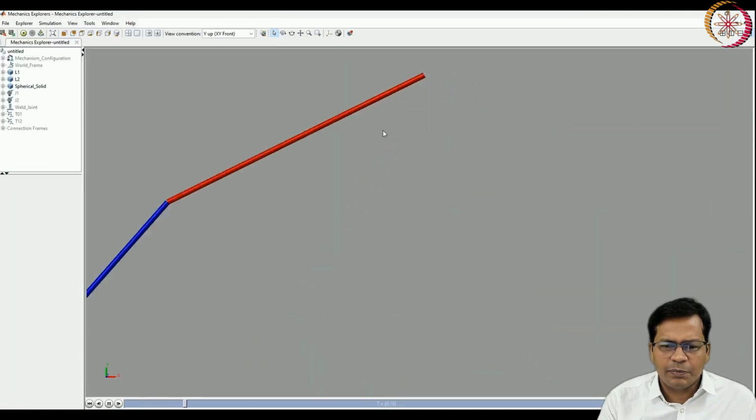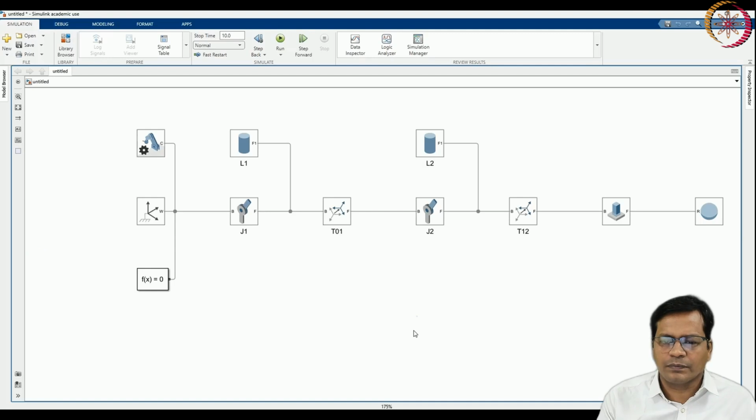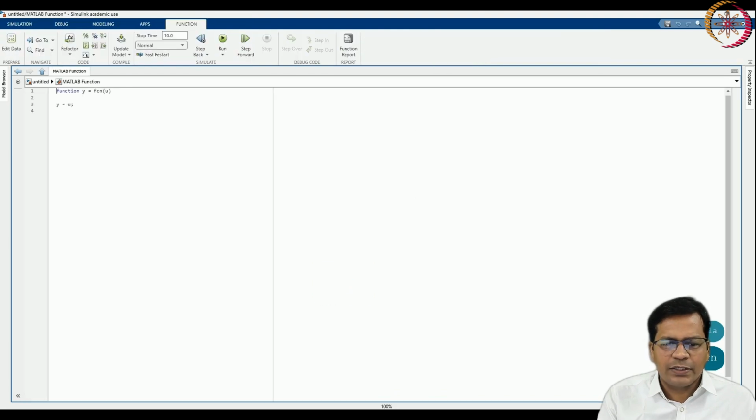Now if I run this, it becomes a 2-link pendulum, and it simply swings because no torque is applied at the joint and it was torque actuated. Okay. Now what I am going to do now that you are ready with your whole system of 2R manipulator with 2 joints and 2 links of 1 meter and 2 meter links. So now you are ready to do anything. So let us start doing inverse kinematics based motion here.